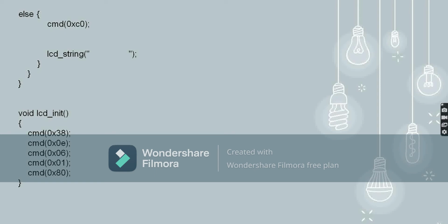When it is 1, the intruder is being detected. Again the screen gets cleared when there is no other detection found. So the next command is 0x80, that is force the cursor to the beginning of the first line. Again it starts from the first line.